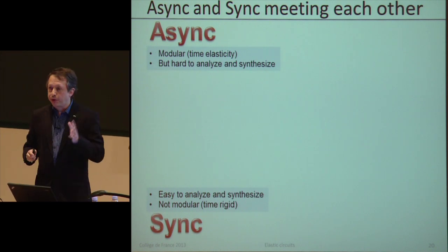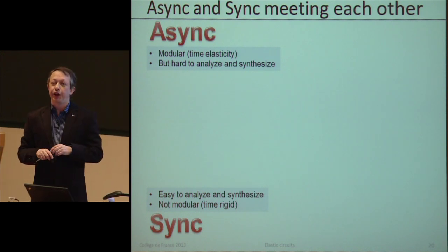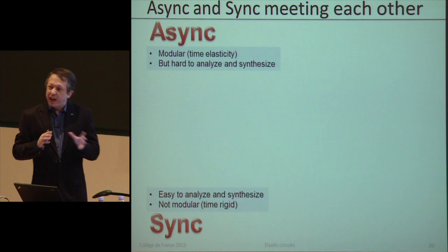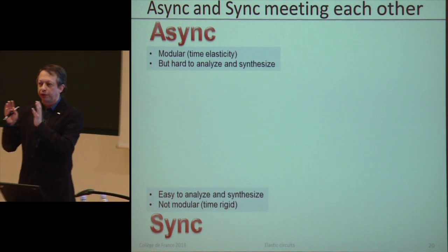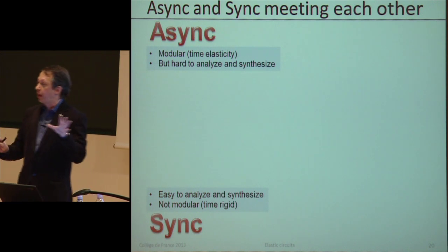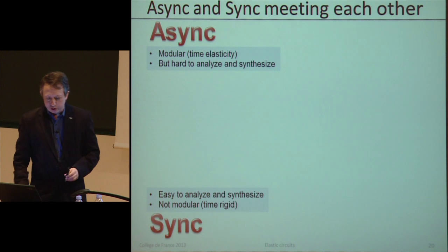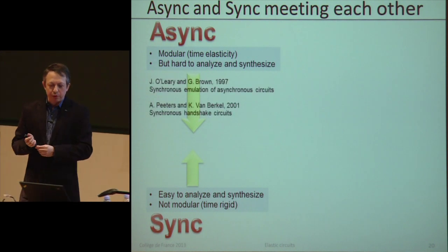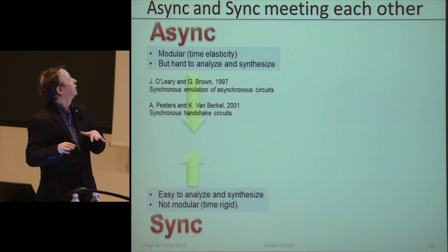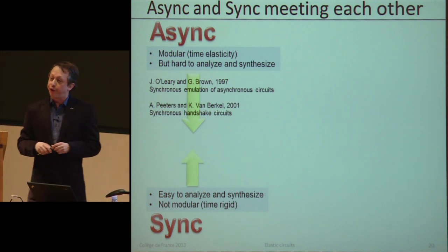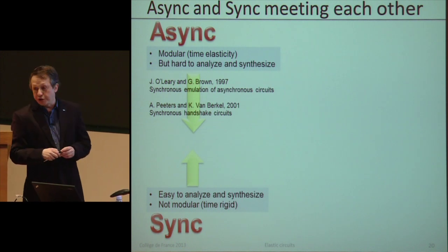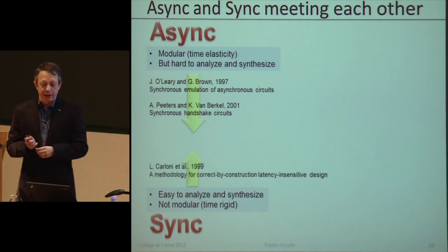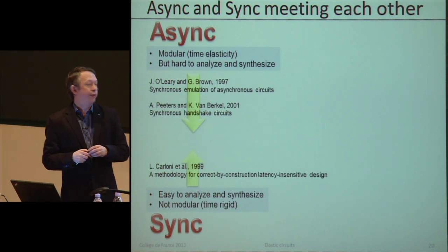In the synchronous world it is the opposite. Synchronous circuits are, I would say, easy to analyze and synthesize, and there is a lot of CAD support for that. But they are not very modular, in the sense that they are rigid. If you change the timing of one of the components, you have to change the timing of the neighbors. So people started making efforts to mix these two worlds. From the asynchronous world, there were attempts to make elasticity synchronous. For example, the synchronous emulation of asynchronous circuits was proposed, and later the synchronous handshake circuits. On the other hand, in the synchronous world, a new concept appeared, which is latency insensitive design by Carloni, McMillan, and Sangiovanni-Vincentelli.